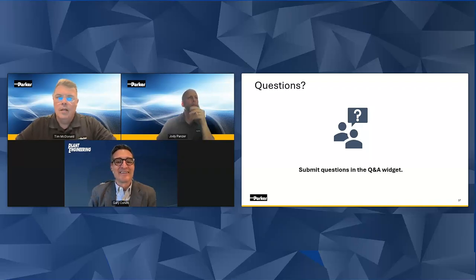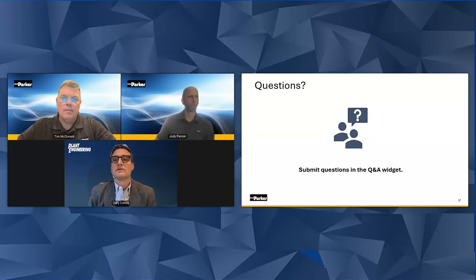Sure, great, thank you. So one of the first questions I have here is, can I design a system with 0 pressure drop? I believe, yes, you can, but some of the things that you have to take into consideration is to get a 0 pressure drop system, the size of the pipe that you would be required to install in your facility may be significantly larger than you need. It also may prevent you from getting the proper velocity from the gas that you're trying to move through your system. So I don't know that you would gain as much from that as might initially be thought.